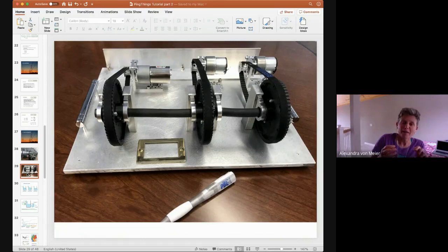But that twist in the rotating shaft is analogous to the voltage phase angle that varies depending on whether you are driving the rotation at a particular place or bus where your generator connects, or whether you're sucking power out of the grid at that location. So in the places where the shaft is doing work on the exterior, it's going to be lagging.